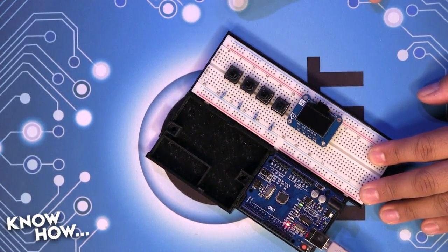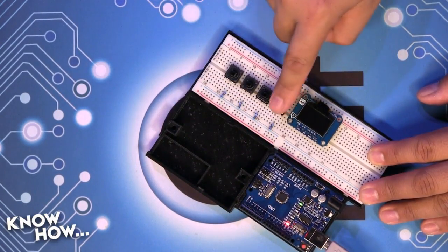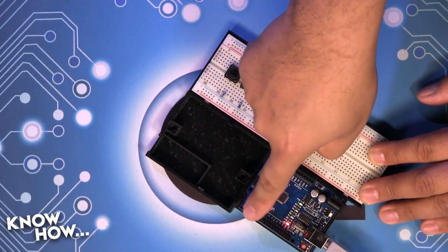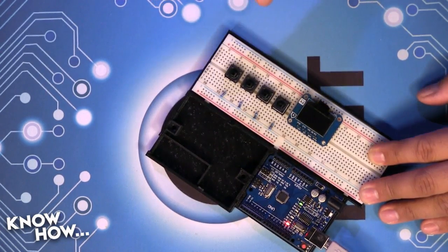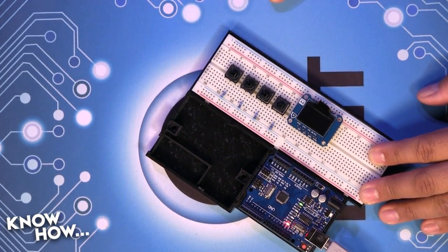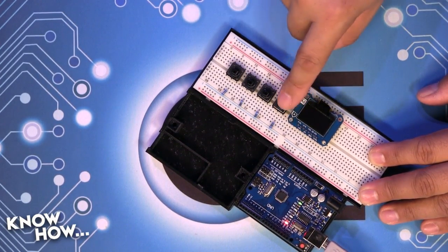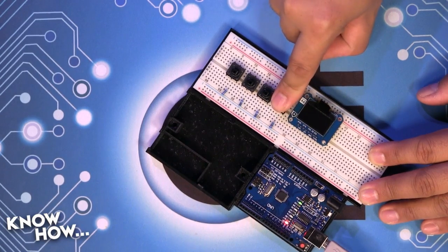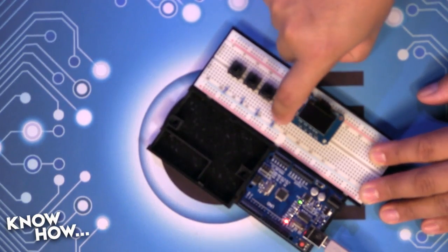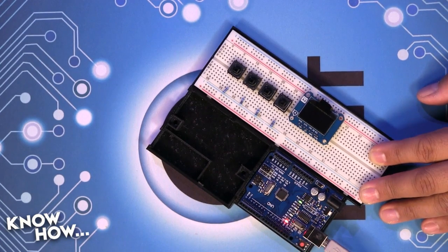And if you remember, the pull-up resistors are so that normally, even if I'm not pressing the button, there's a current going between the ground pin and the pins I'm going to be using to read it. That's because the pins aren't really on or off. They can detect high and low current. And if it's off, it's not high or low current, it's no current. Right, which is not something that the Arduino can detect. It's not designed to detect. So when I push the button, it actually shorts. It's going to go from current through the resistor to current without the resistor, and the Arduino can measure that. It knows the difference between a tiny bit of current and all the current.